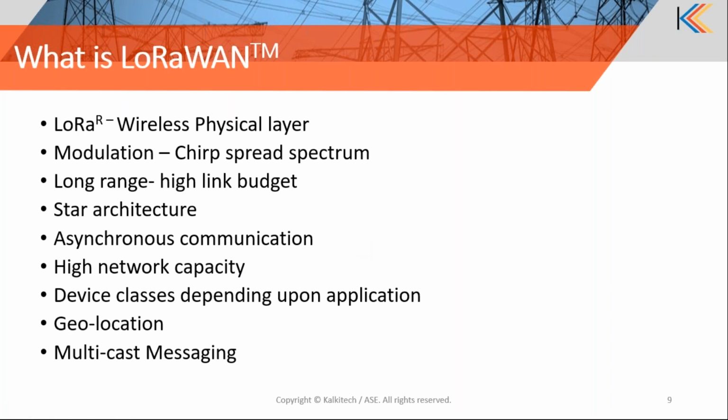Basically, it uses a mechanism called adaptive data rate, or ADR, to adjust the data rate to suit the environment. If a device is closer to a gateway or base station, it will use less power, less time on air, and higher data rates. So all the devices closer to the gateway will communicate faster on a high data rate, which means other devices farther from the gateway will have more time to communicate. Similarly, end devices located at far points will use higher power and lower data rate. With a lower data rate and higher power, it ensures that data from nodes at further points will always reach the base station.